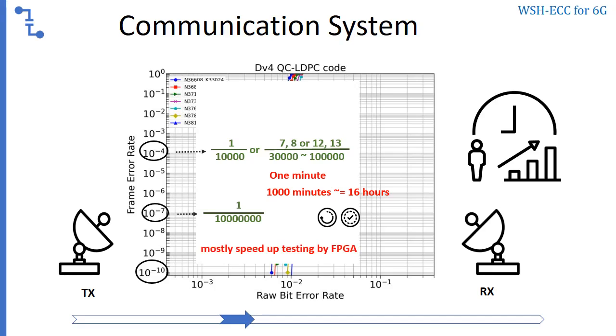If a potentially suitable candidate is selected and the sensitivity to decoding is further tested with other settings, large error rate fluctuations due to reliance on unreasonable soft decoding may be uncovered. I am sorry to say, discard this and move forward to test the next. After going through a full process, for a multi-length ECC family, you need to examine every ECC mode. Maybe parallel processing can speed up testing, but running 20 or more sets of long-term simulations at the same time is tedious and tiring work. The ECC coding quality depends on the patience of the designer. Most players did it by lowering the verification criteria. When someone wants to improve quality verification, they are faced with the current market situation where bad money drives out good.